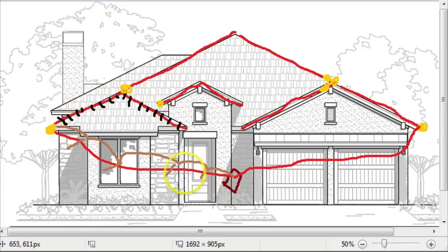So, in that case, these pixels are not actually there for functioning in terms of output, but just there for phantom output. So, that varies. That feature is most often available on large centralized controllers, but we generally recommend decentralized controllers where you're putting the controller near to where your pixels are located for outlining houses.